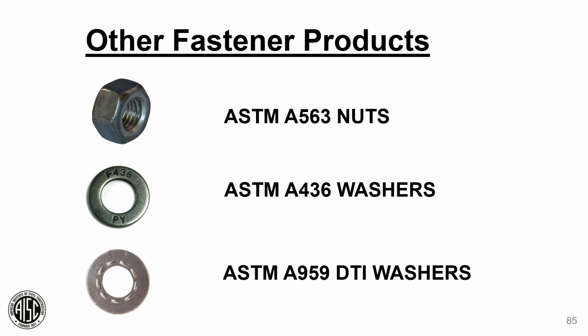Now, the preferred material for hardened washers is ASTM F436. Now, this specification covers both flat and beveled washers. They recently added an extra thick option that was added for cases where the RCSC specification in Table 6.1 requires a 5/16 inch thickness when oversized or slotted holes are used in the outer ply of a steel-to-steel joint.